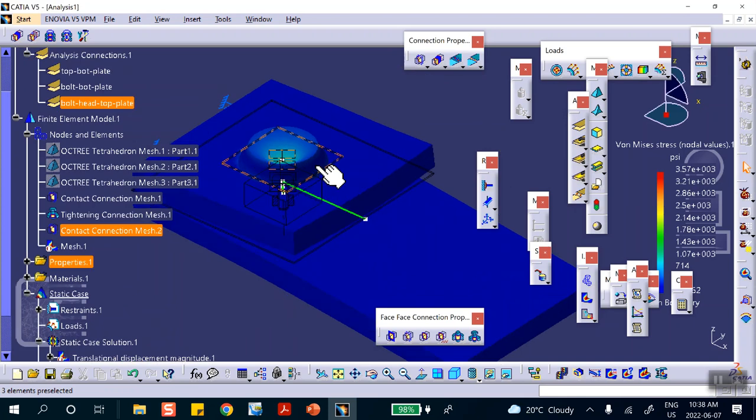Now, there is a problem. The level of confidence that I have in these things or accuracy depends on the extent that you model these things. For example, look, this bolt was exactly the same size as the hole because I projected same size. When you tighten it numerically, it actually goes sideways to the hole, and it penetrates it.